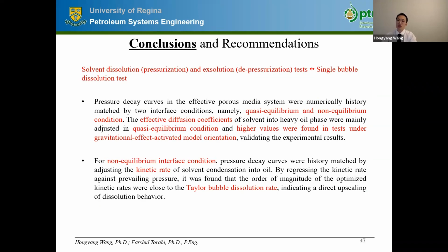And the solvent dissolution and exsolution tests, mainly the dissolution here, was compared with a single bubble dissolution test. And we have found that by using two different interface conditions, or we call them boundary conditions, which are the quasi-equilibrium and a non-equilibrium condition, the effective diffusion coefficient was tuned to history match the pressure decay results in the quasi-equilibrium condition.